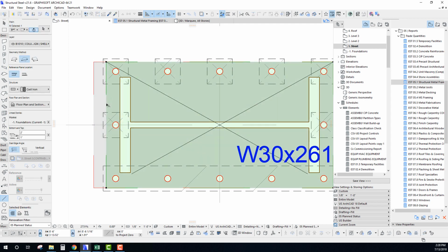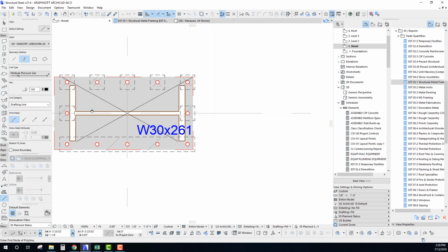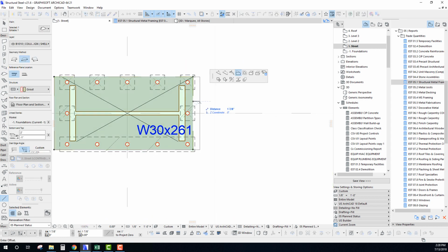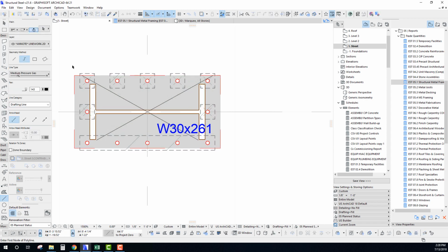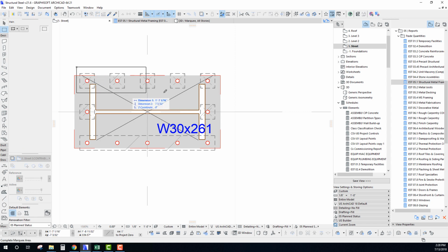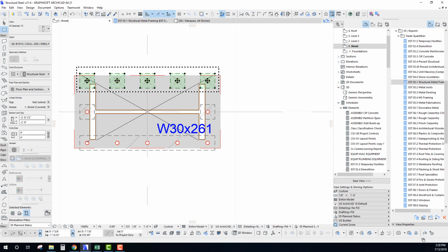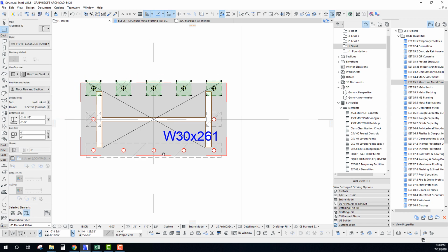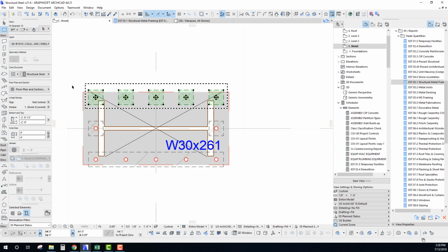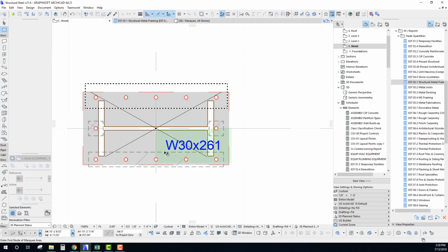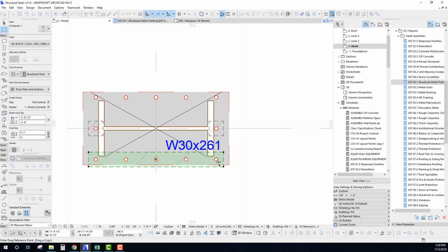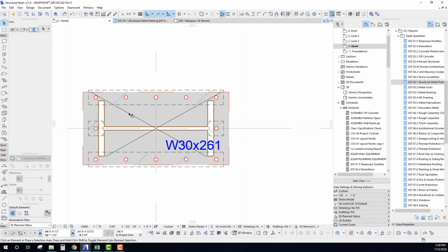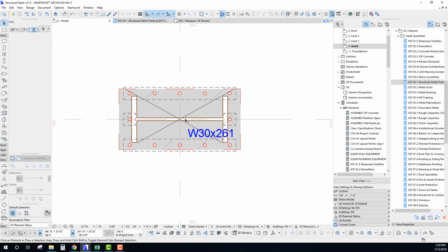And so what we might do is maybe let's extend this out another 2 inches. And we actually have 2 slabs here. We have one for our steel and one for our grout. So I'm going to push this out in both directions. And maybe in this case I want to use a strip anchor plate versus the individuals. So let me just deselect these right there. So let's delete this, and I'm going to take this and pull it over. And so, okay, so there we go. That's close enough for our base plate assembly.